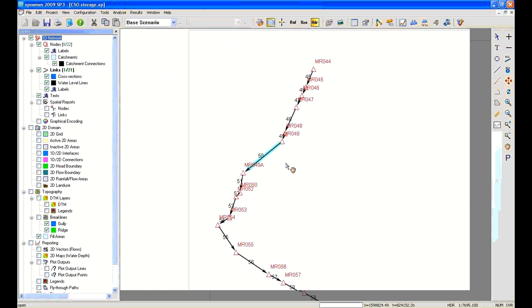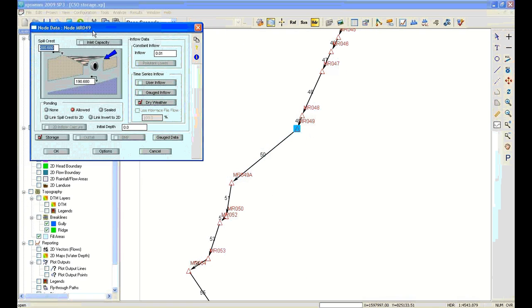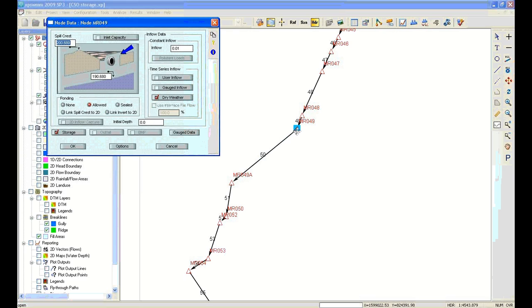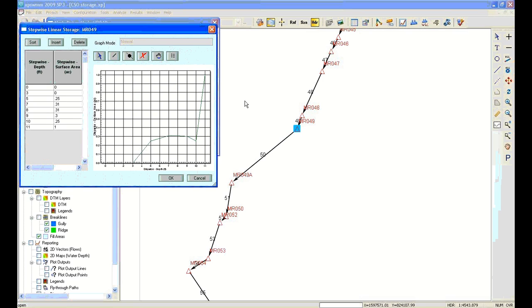And what I did with this, just to give you an idea of how I modeled the basements, is I put a node in each storage facility in each node, and I just assumed, for the sake of this operation today, that we would have a 15 by 45 foot long basement, and so I said that they sit somewhere between 5 and 6 feet above the bottom of the pipe, so they're not completely deep, not as deep as they could be, because this is a 10-foot deep area of sewers.